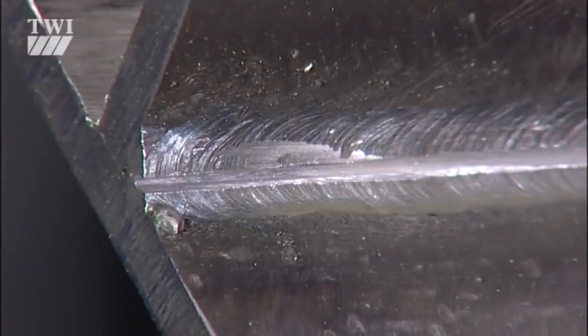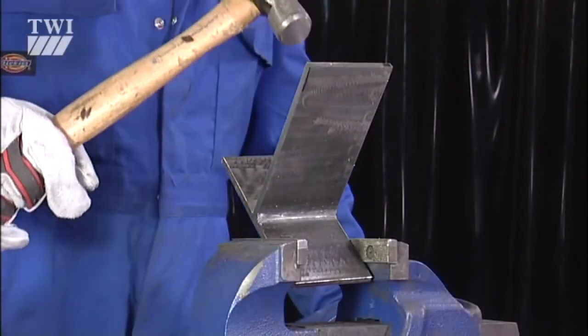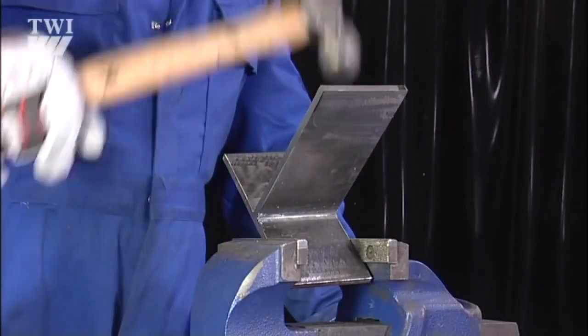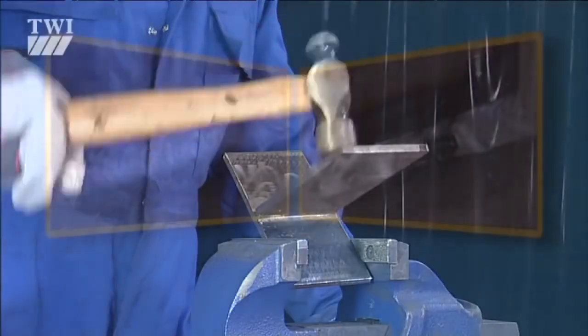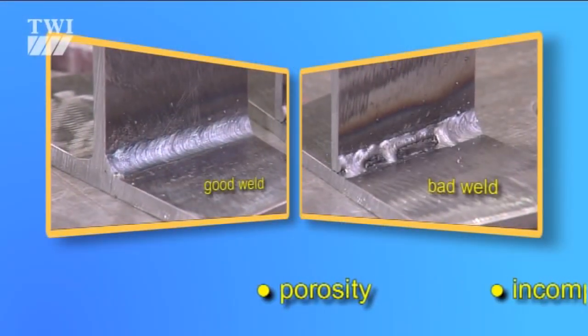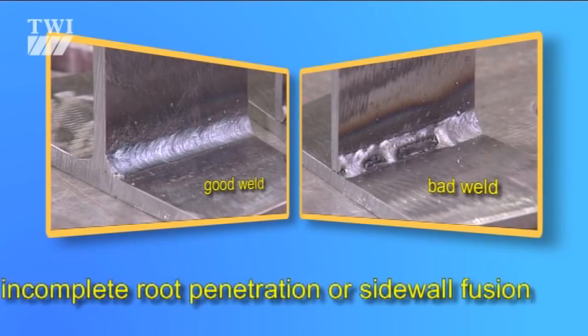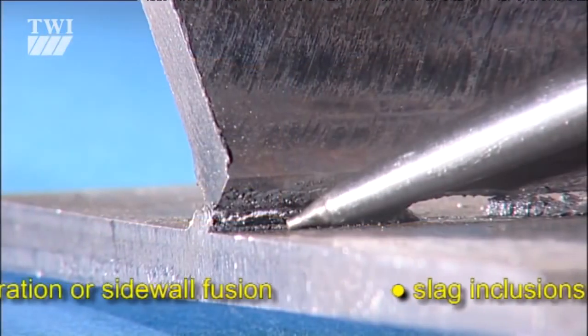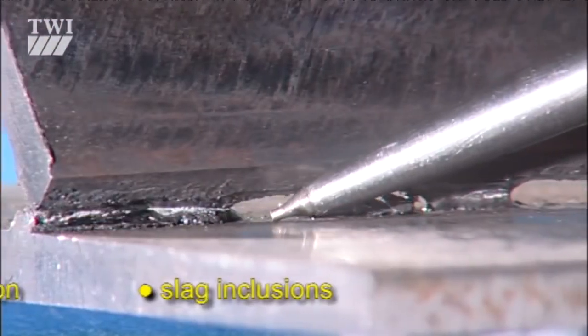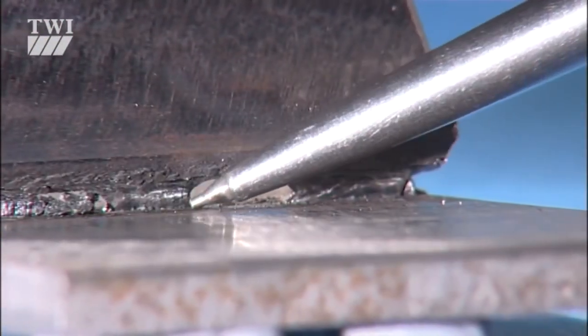Force is then applied to the specimen to bend open the weld using a testing machine, a press, or blows from a hammer. The fractured surfaces can then be examined for internal defects such as porosity, incomplete root penetration or sidewall fusion, and slag inclusions. Well, that about wraps up this brief introduction to mechanical testing.